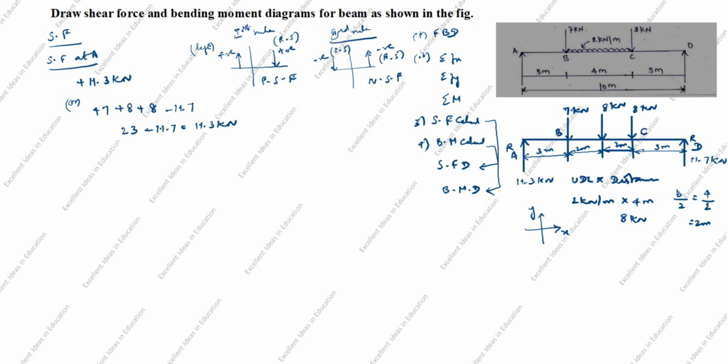What is the shear force definition? Algebraic sum of the vertical forces acting to the left or right side of the cut section along the span of the beam. Next, we will calculate shear force at B.